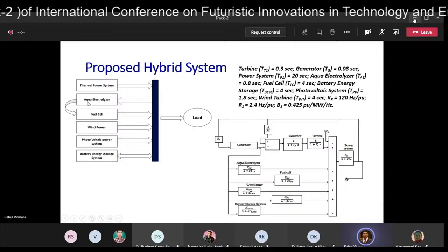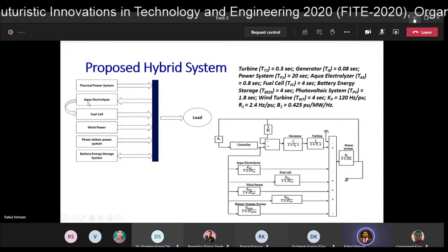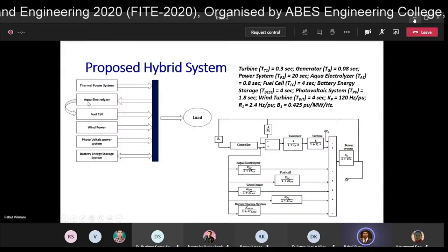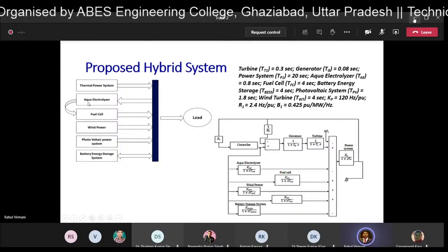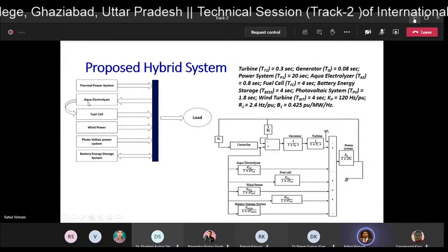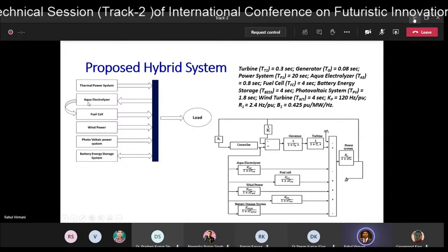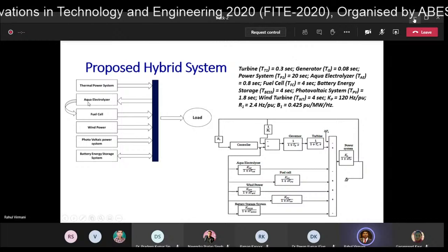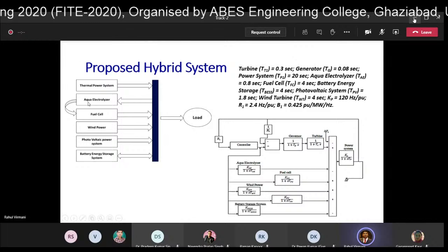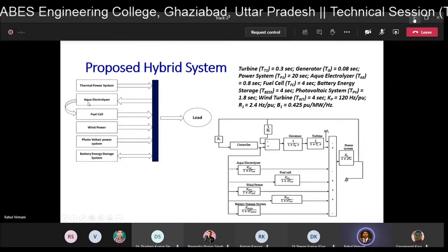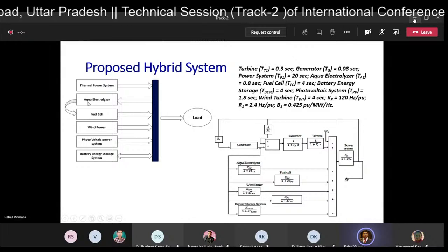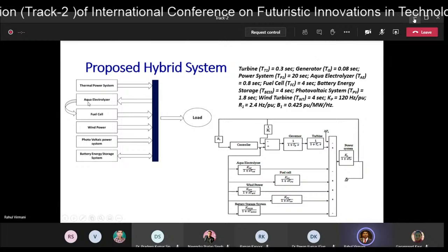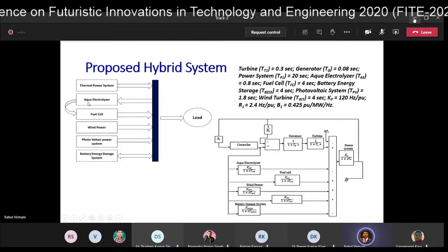Now, this fuzzy controlled fractional order PID controller is better if better membership functions, the input functions and the output functions, are mapped. Now, this process can also be done by using many intelligence techniques such as PSO, ant colony optimization, or bacterial foraging optimization.